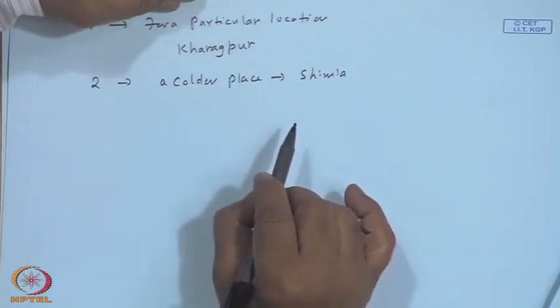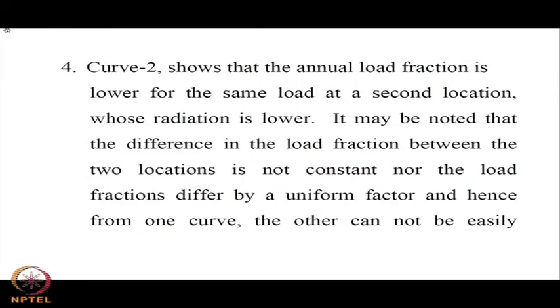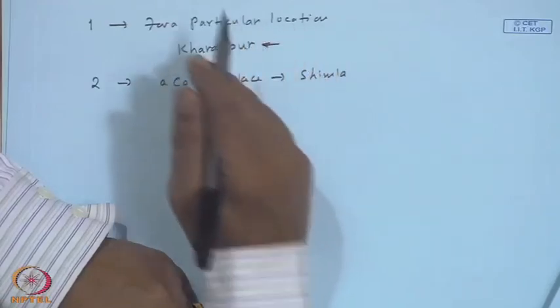Useful energy delivered by the collector is lower and the load also is higher if it is a space heating system, or even if it is a water heating system, simply, your T ambient or T minimum inlet temperature to the collector will be much lower than what it could be in Kharagpur or Chennai.